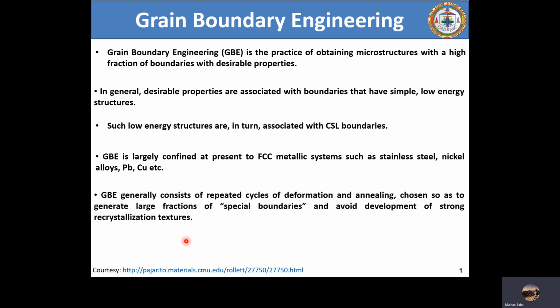Okay, in an equilibrium microstructure, I must say. Those boundaries are getting preferentially corroded because of their high grain boundary energy, and especially if they are random high angle boundaries, they will have a higher tendency of getting etched or undergoing preferential corrosion as compared to a low energy boundary. So there's a reason why we are able to see the etched microstructure. But there's also the problem of over etching, because if a microstructure has too many high angle boundaries, especially in the recrystallized condition, too much of high angle boundaries rather.